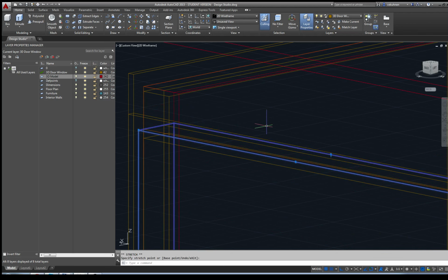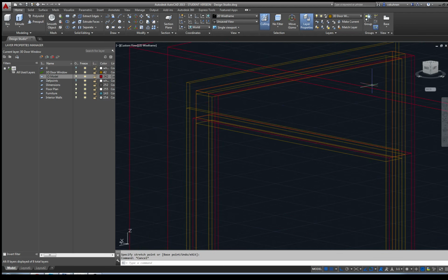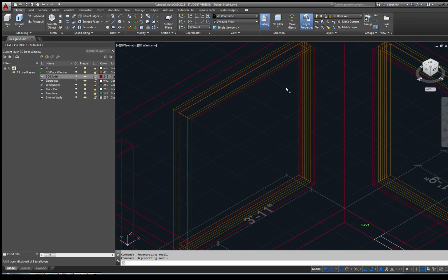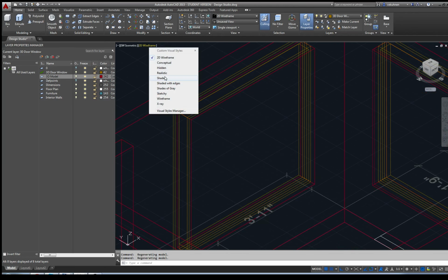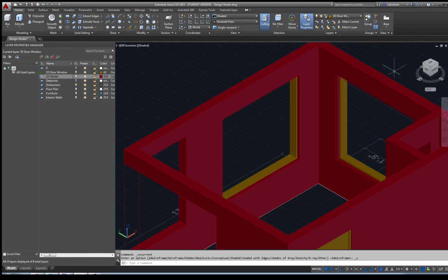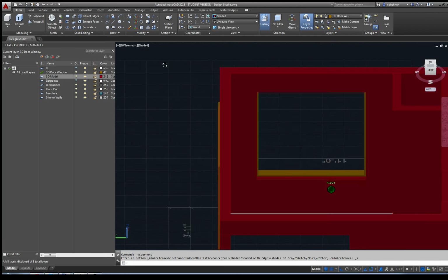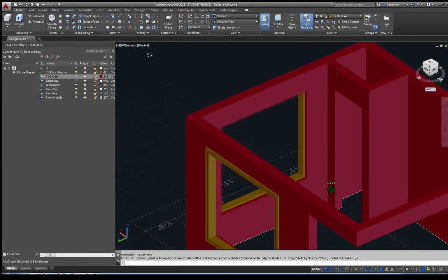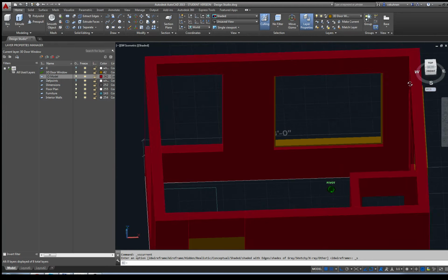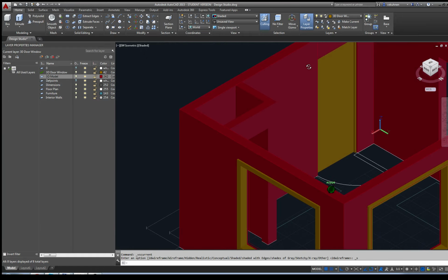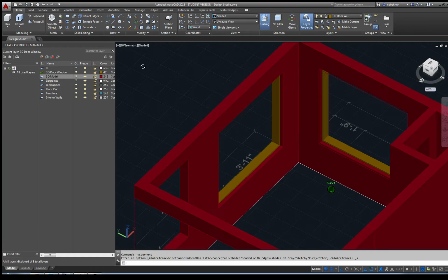Click, and I think this should have done it. Let's take a look. Yeah. See, perfectly helped. The perpendicular actually made sure that I was moving the upper edge of my window down, so it snaps perpendicular onto my window frame. Let's go into this view and let's rotate it. And yeah, so there we see. Perfectly fits. So that's, for example, how I created the opening for kind of like a window.